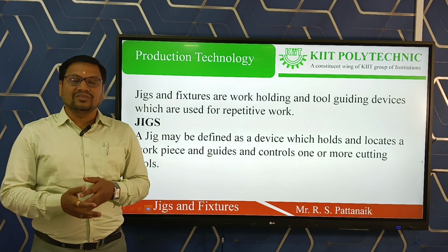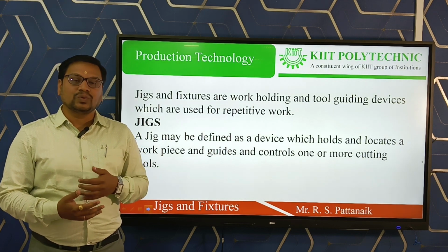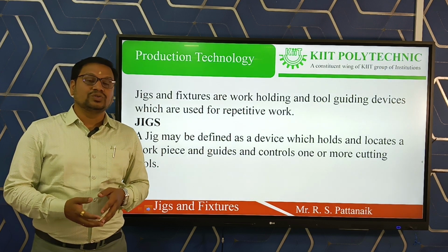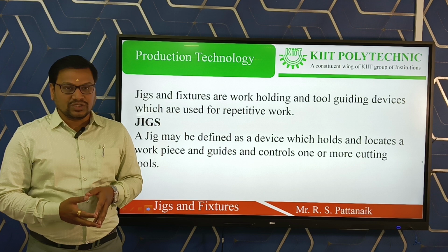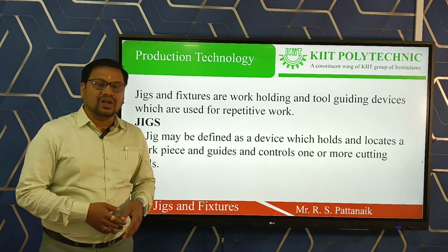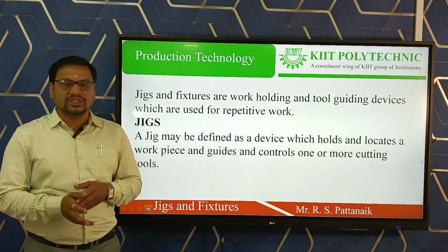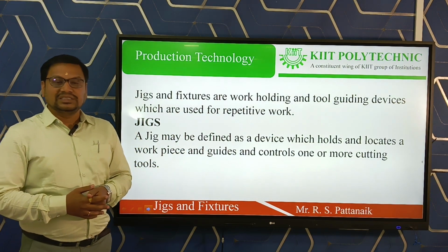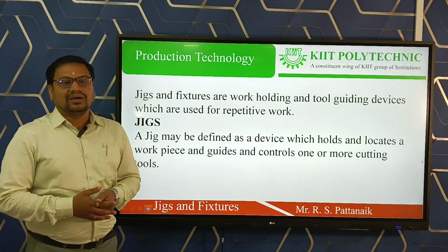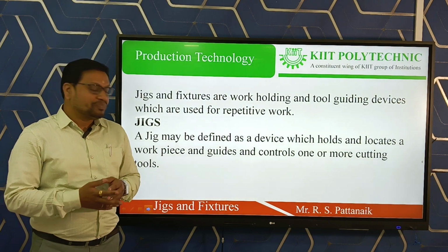A jig is a device which holds and locates the workpiece and at the same time guides and controls one or more cutting tools. Jigs are basically used for operations like drilling, boring, reaming, etc.